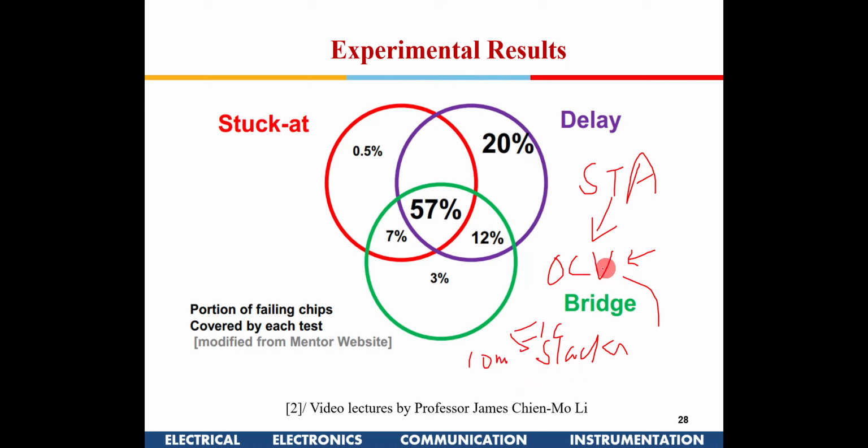We will cater for 10% variation which will come during fabrication, from voltage variations, temperature variations and so on, and we might want to keep it at, say, 12 nanoseconds, so that even if there are some delay faults while getting fabricated, the setup constraint is not violated. So when we do static analysis, we will see that. This portion is really taken care of during our STA analysis.